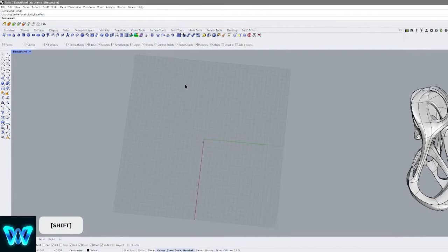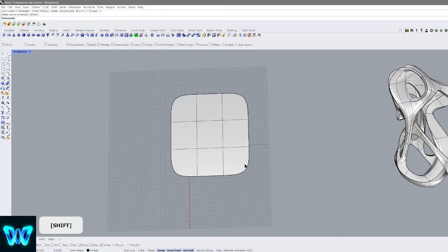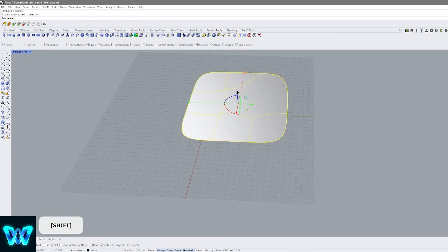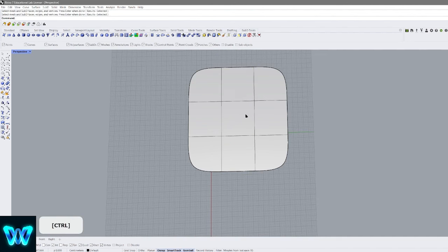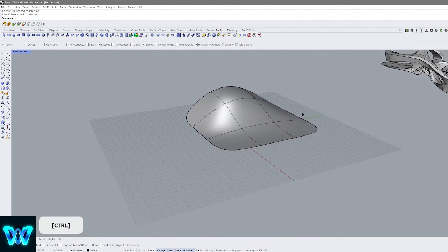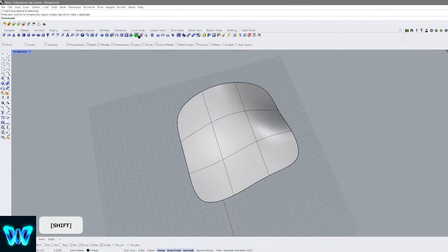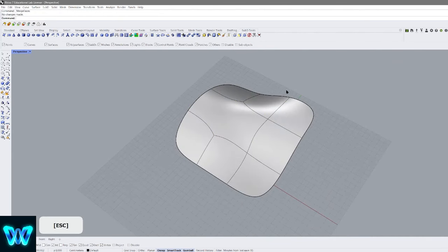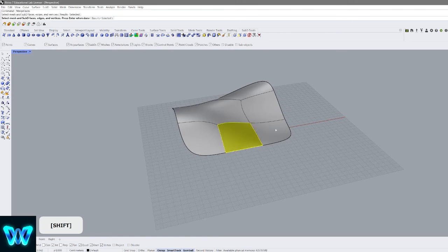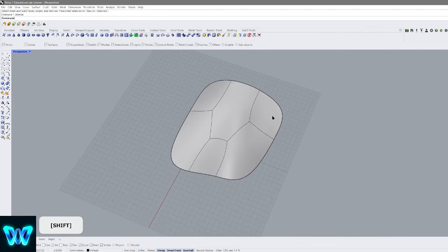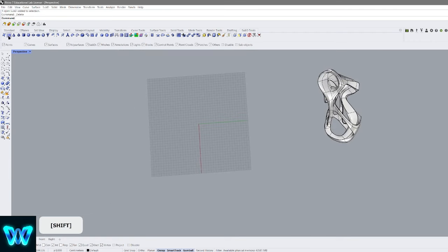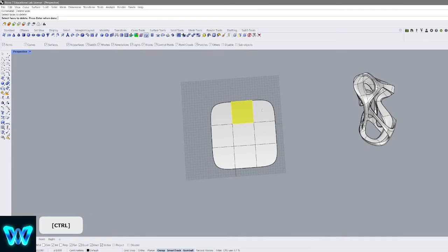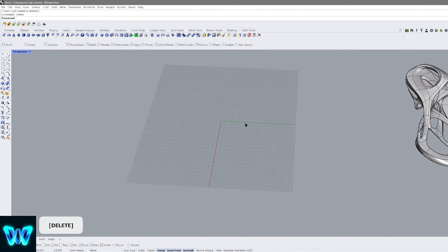Here, right here, you have merge faces, which just merges the faces. So here, I mean, it's the same as coplanar, but it doesn't have to be coplanar. So it might work weird at times, because if things are not coplanar, let's see. I move this around. I merge faces. It's a better coplanar merge, I guess. So it just merges things without having to worry about coplanars. But yes, here we have delete faces. All it does is just, as it says, delete faces. But you can always just select and delete at the same time.